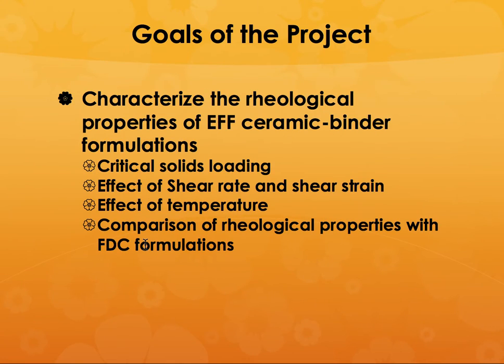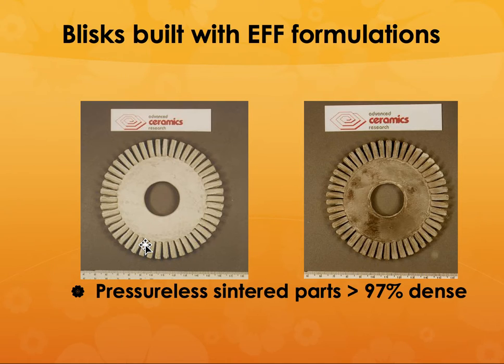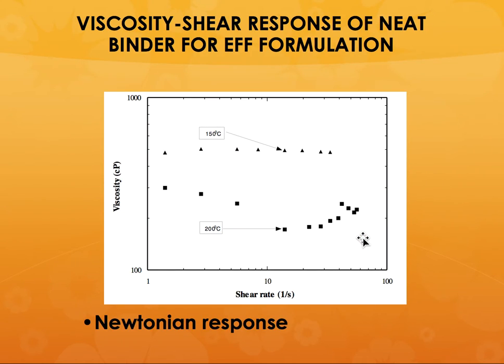So let me go to showing the different kinds of parts. This was the bladed disc, after sintering, of course, because this is sintered in a powder bed of carbon. Sometimes that carbon can interact with the silicon nitride material and leave behind some kind of color difference, but it doesn't do any harm to the mechanical properties of this bladed disc itself.